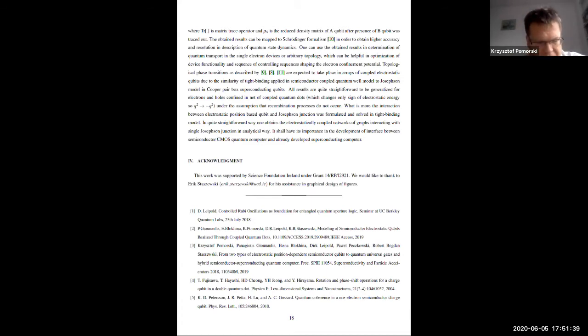It's difficult to connect superconducting electronics and semiconductor electronics because of the size of the superconducting order parameter, the energy gap. If you apply more than 10 millielectronvolts, most superconductors go out of their superconducting state. So you need to play in a delicate way. So I would say in this paper, which I was just discussing,